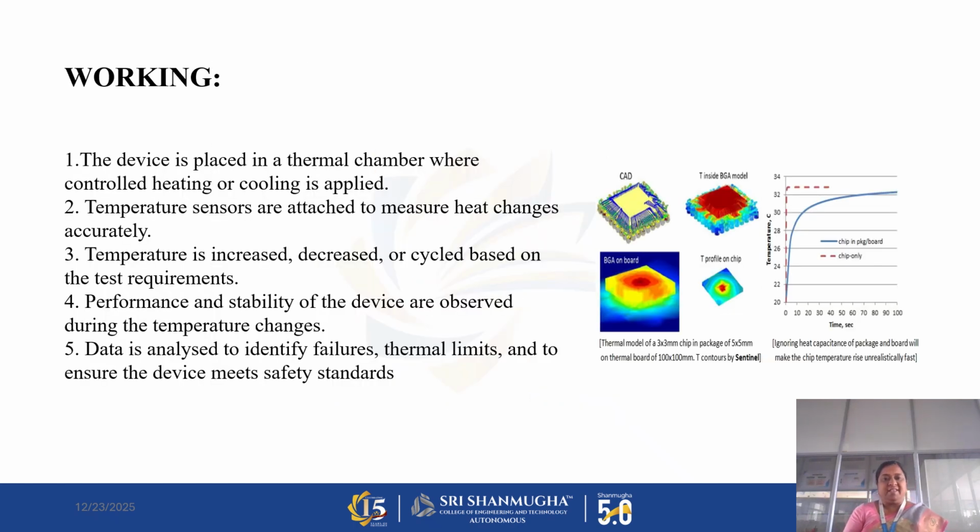The device is placed in a thermal chamber where controlled heating or cooling is applied. Temperature sensors are attached to measure the heat changes accurately. The temperature is increased, decreased, or cycled based on the test requirements. Performance and stability of the device are observed during the temperature changes. Data is analyzed to identify failures, thermal limits, and to ensure that the device meets safety standards.